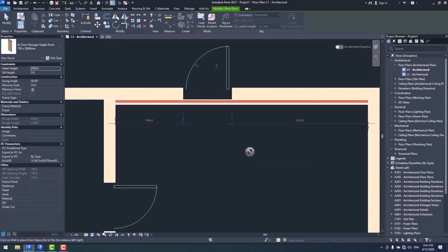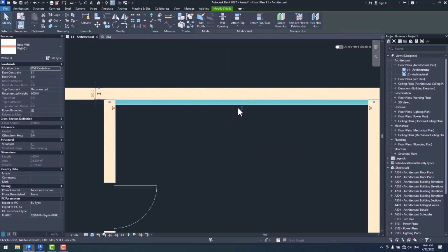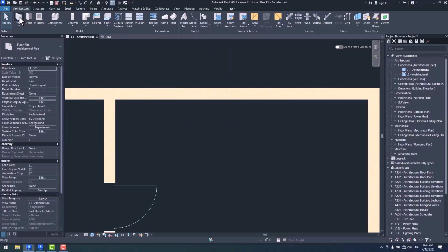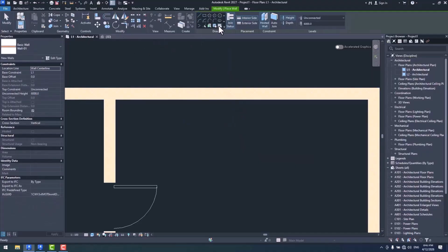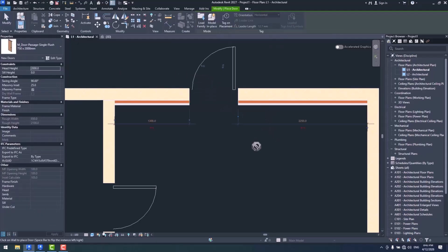So then, what we get out of this is that when using place-based segment and hosted walls, we also need to be activating the auto join option. This way, we can make sure that the required openings for doors and windows, for example, within the walls would correctly be created.